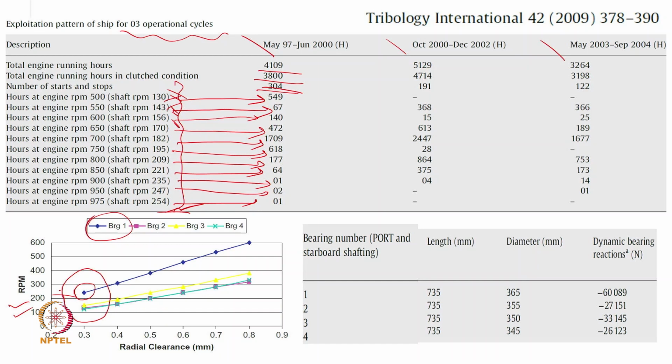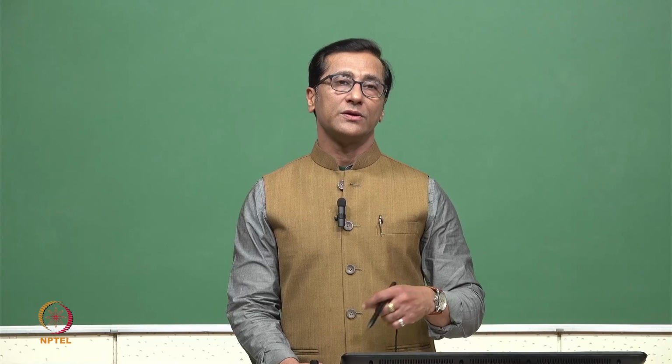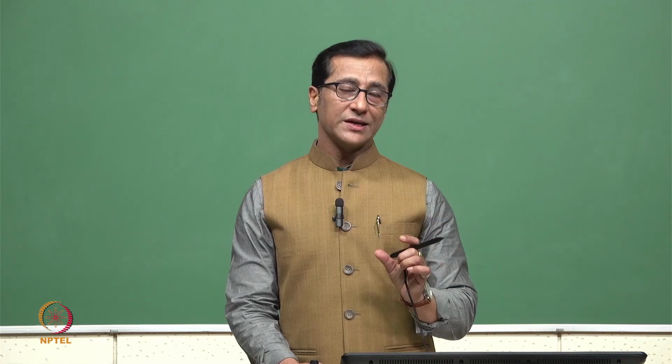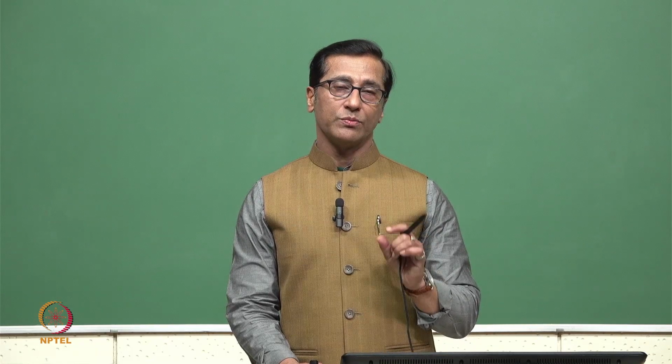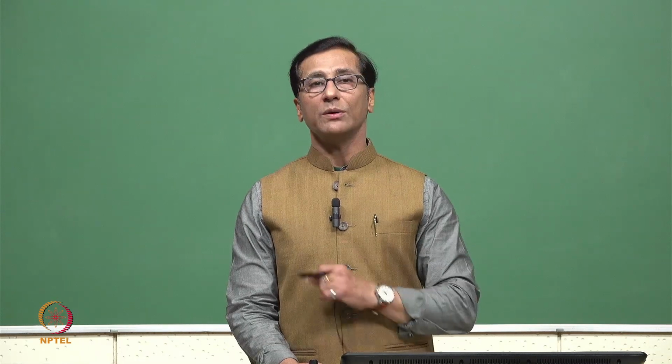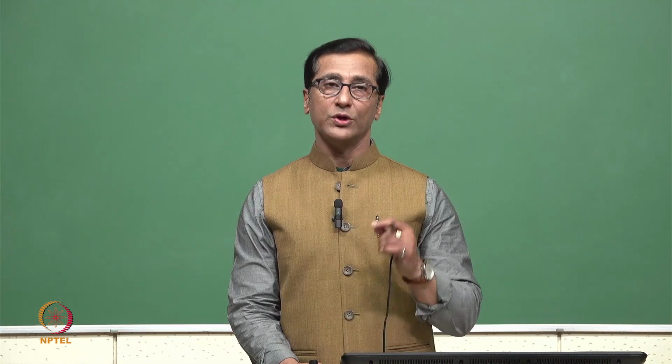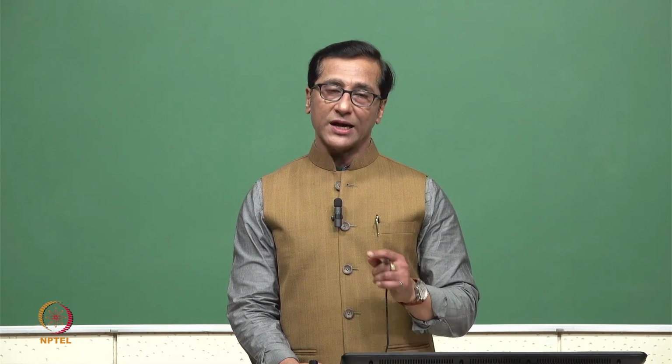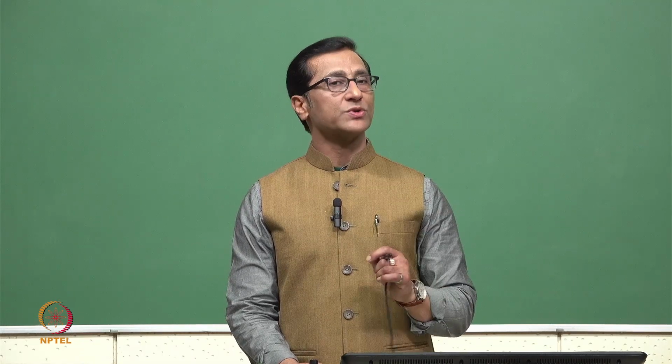What should be done, and this is very important to keep in mind: friction, wear, and energy loss. Friction and energy losses are directly related, but many times to reduce the friction, we are pumping lubricant, we are pumping water from a sump pump, we are forcing it. That pump also will consume some power.